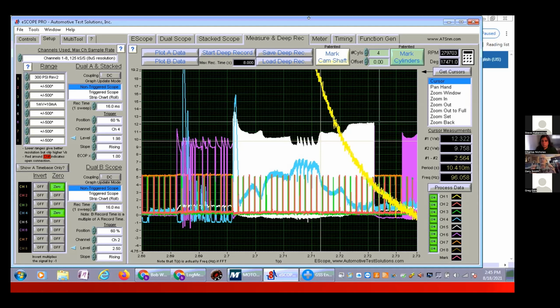And beyond that, if we take that Kirchhoff's current law into effect that you and I were studying the other day, and we agree that throughout this current operating range, we should be at or near zero. And when I say or near zero, Kirchhoff's current law works beautifully in math, but in reality, as that motor or phase is cycled on and off, you've got inductive movement between the phases, which is creating slight movements off of zero, if that makes sense.